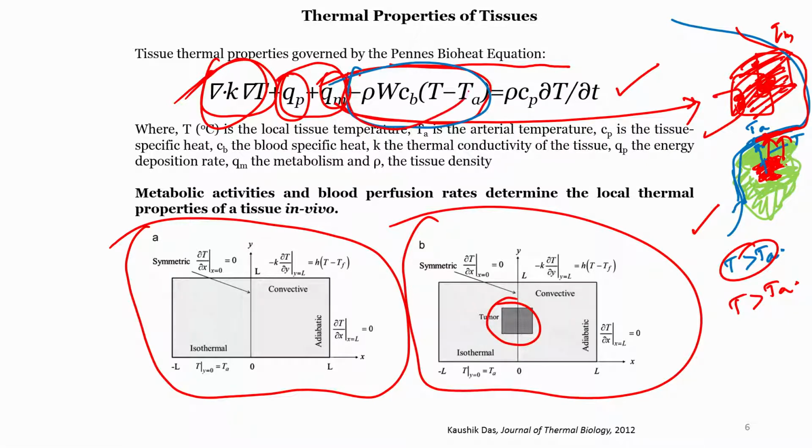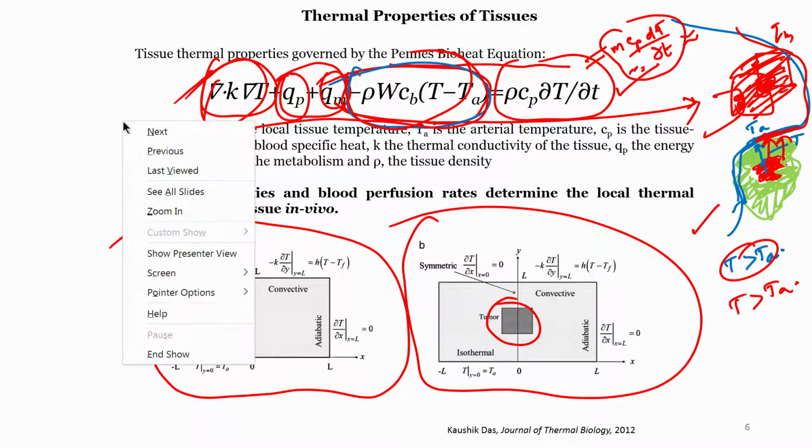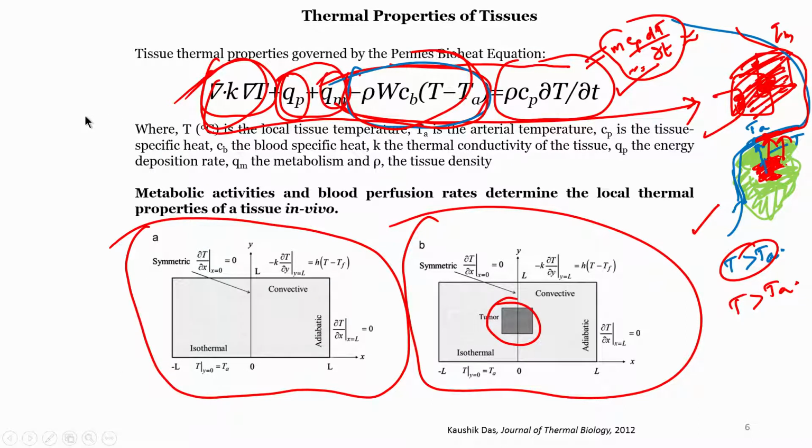This is that term, and this right side term is basically how effectively all these competing factors contribute to the increase in the tissue temperature. This is basically another form of the mCp dT equation divided by time, ∂T/∂t. So, this is like a power per time, change in temperature per unit time, and what all factors contribute to this is what we have seen in the Pennes' Bioheat equation. So, it is a very important equation to model the bioheat parameters. Okay.